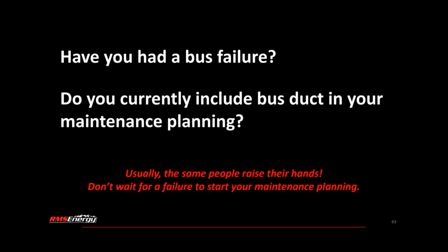Well, there could be a couple different causes. It sounds like you've investigated the grounding and the gasketing, because sometimes that's used for isolation there, and that can lead to circulating currents and eddy currents. But that might be something that we can investigate offline. 20 degrees Celsius isn't a huge concern, but I would definitely suggest to monitor it and make sure that it doesn't progress any worse.